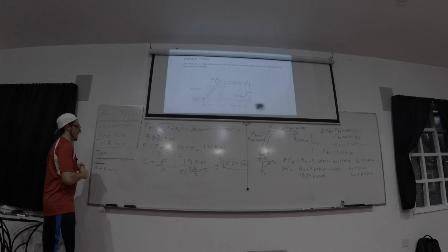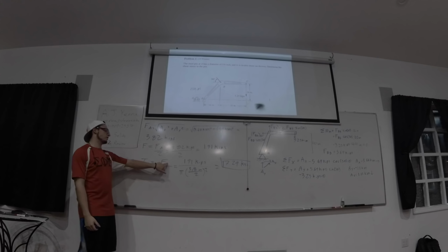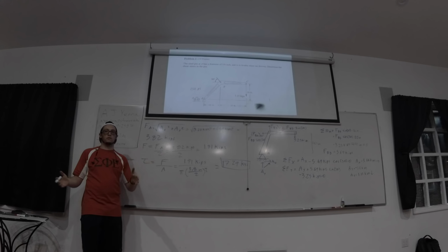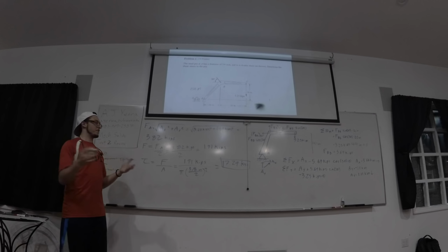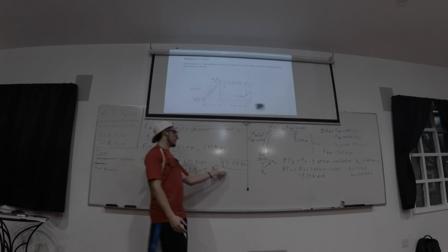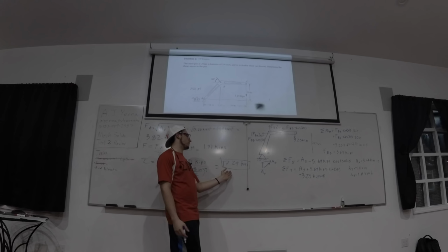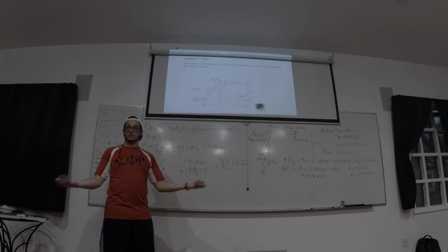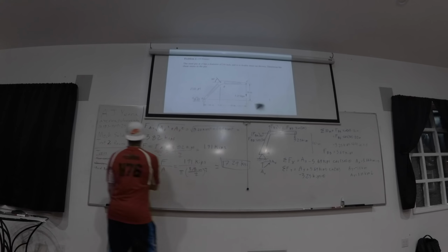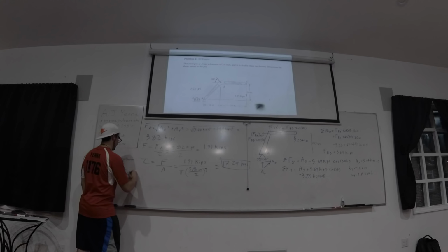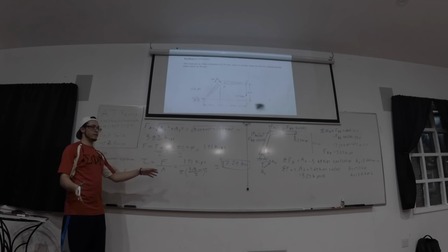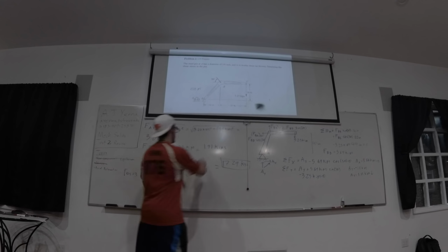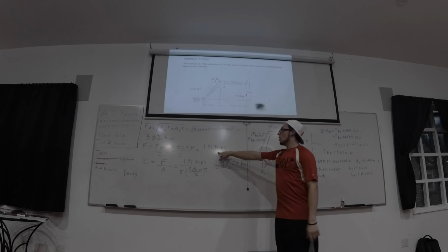So very simply, what factor of safety does is it decreases the force you're using so that you have a buffer in between there and the force. So if they say the thing can physically withstand 17.29 KSI and it has a factor of safety of 3, for example, and you back calculated everything and you found that your F was equal to this 1.91 kips, you're going to take that 1.91